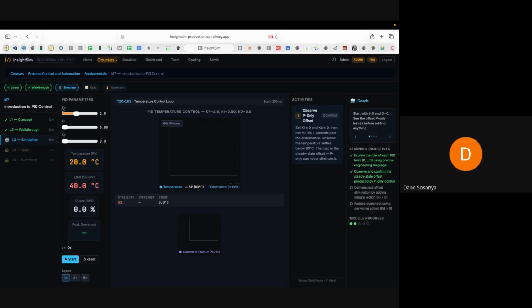For a fail open controller, the minimum, for a fail close rather, the maximum will be 20 milliamp and the minimum will be 4, right? So you need to match the output from the controller to the movement, to the design of the valve. For you to understand this relationship clearly, you first need to learn how a valve responds, I mean, the configuration of valves. How are they open or closed? I think I've done that explanation some time ago.